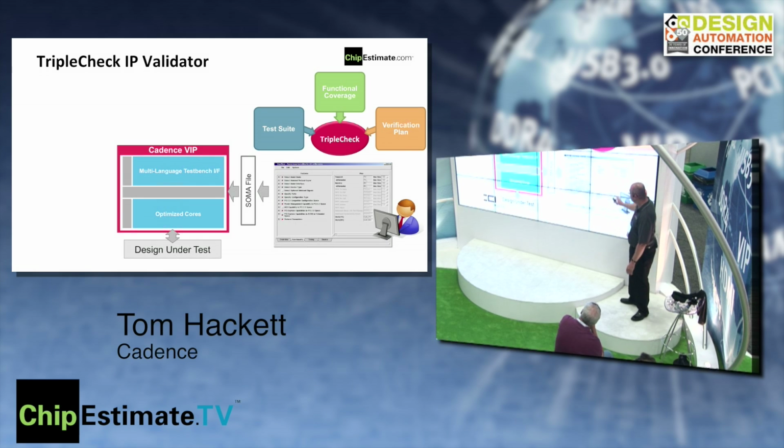And so with this user interface, you'll start to select checkboxes to say, okay, my design is a root complex, and it has, say, 16 lanes, and all the other different things in PCI Express. And when you click each one of these categories, it opens up a new window and presents to you the things that are logical for a PCI Express root complex with 16 lanes, okay? And if it's generation 1 or 2 or 3, etc. But with all that, it sets up the VIP to match your design. So that's an otherwise time-consuming task that this process saves.